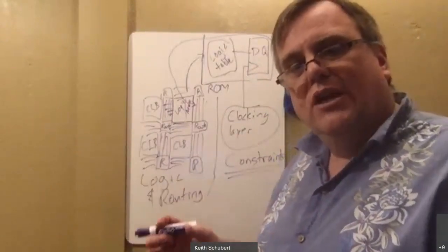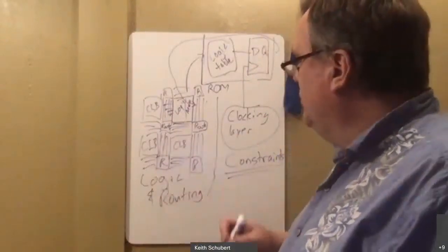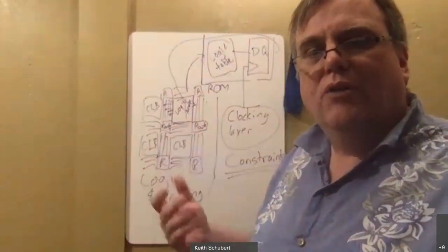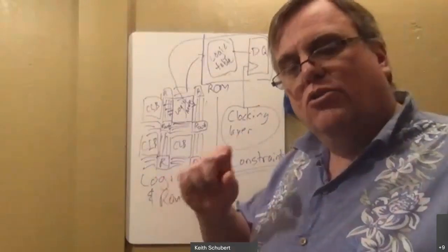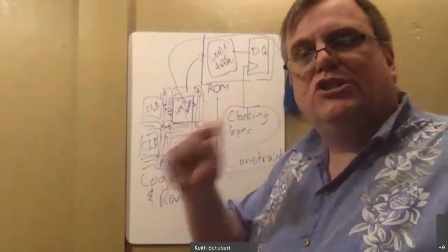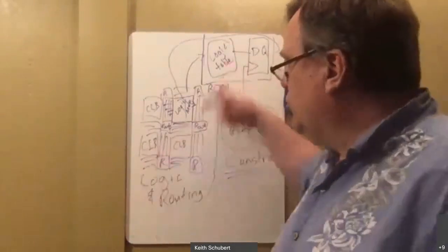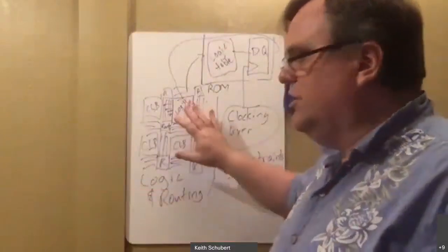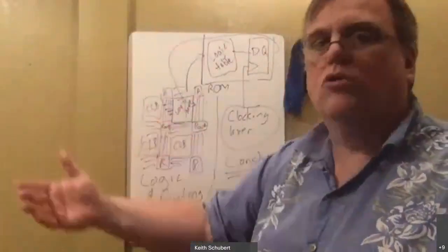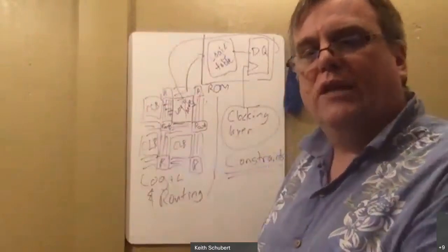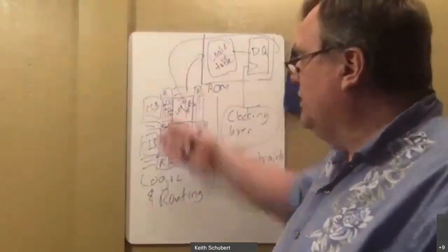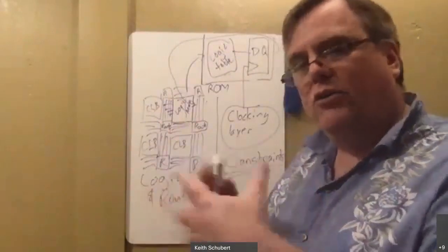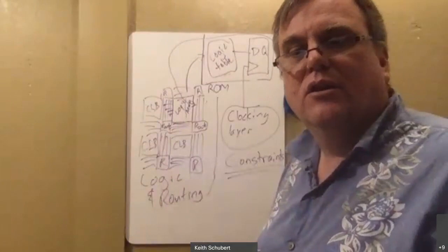Therefore, what happens is the longer the route, and now if you consider what you guys were doing, I believe you were doing counters, and your counter, when it's going in, the smaller digits change faster, so they're going to have shorter routes. The larger digits use the earlier digits plus themselves, so they've got a really long loop. So the further you get, the bigger the digit, the more these errors will get exacerbated, which means the more the digits are going to get weird values and flicker and do stuff like that.